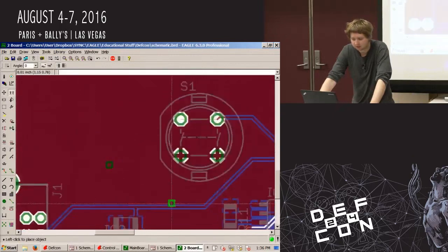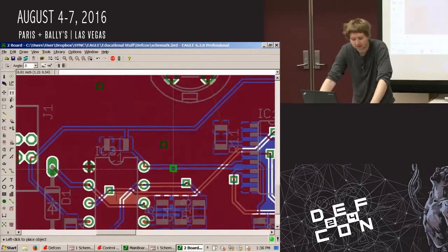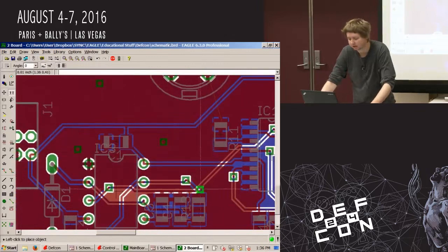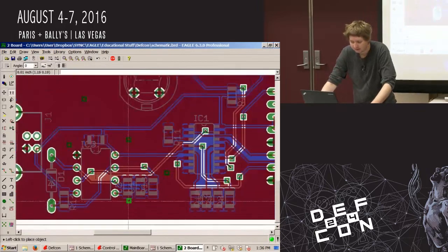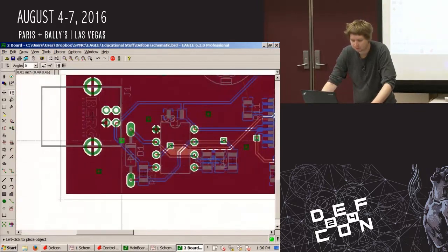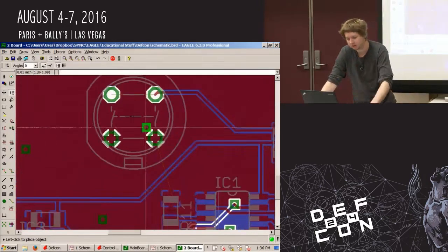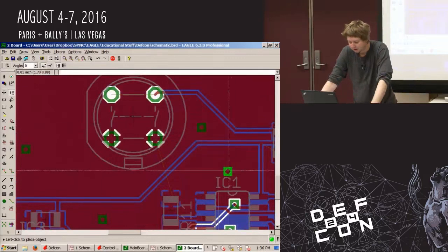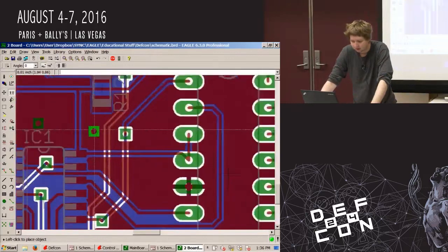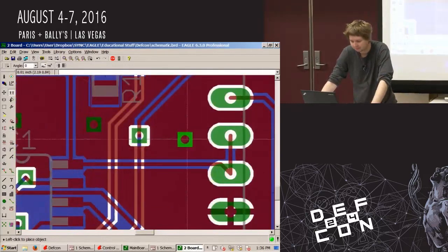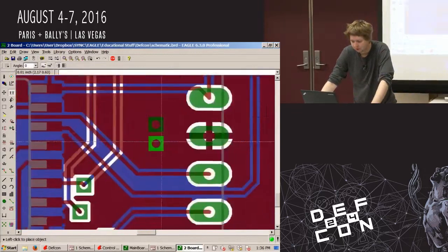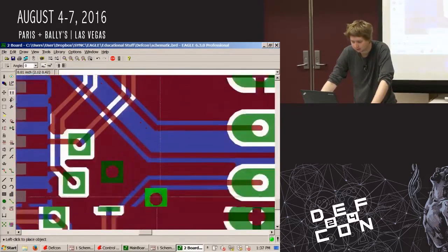From here, I just clone this a bunch of times, and whoever has my circuit board will see that I just went nuts with this. And I do this because it helps short out any kind of high frequency signals you may get, and it also allows you to keep a low impedance with all of your grounds.